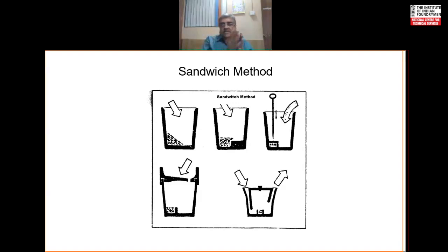In some cases, I have seen this particular process, the third one, where the pocket is sealed. I have seen it being sealed by sodium silicate bonded sand. And then after the metal has been poured, the pocket is opened by poking it with a bar, a crowbar, and allow metal to react with the treatment alloy.